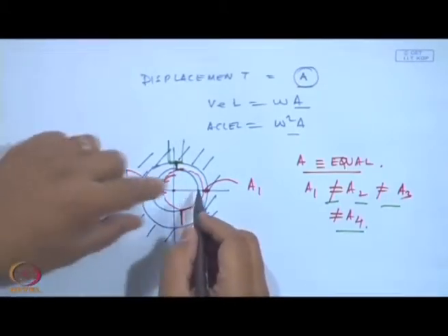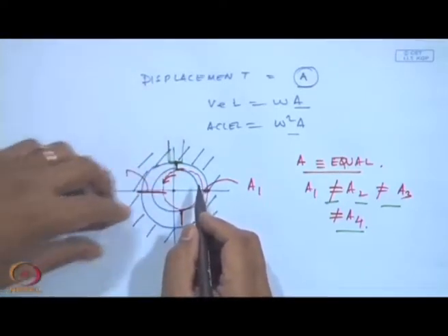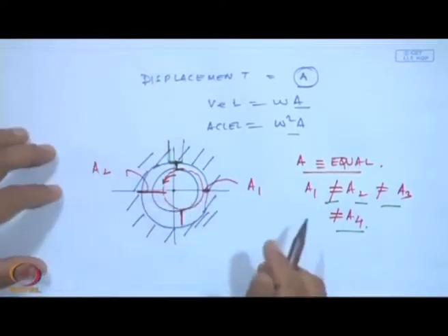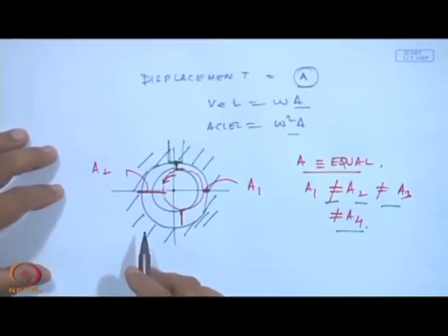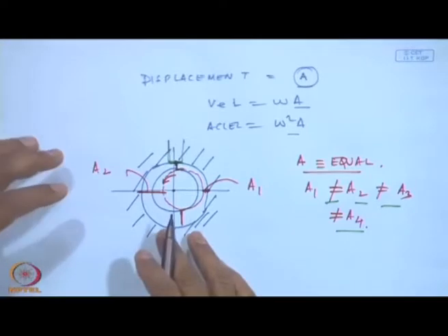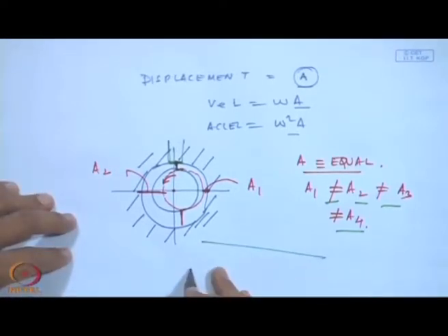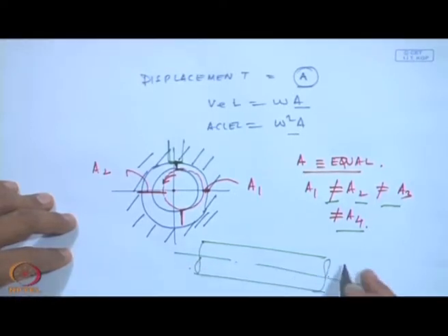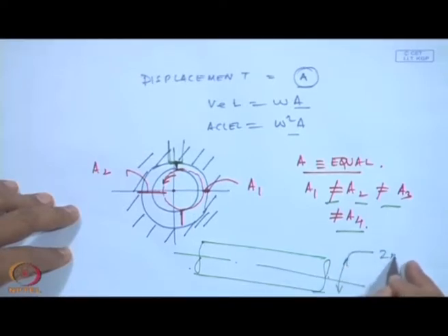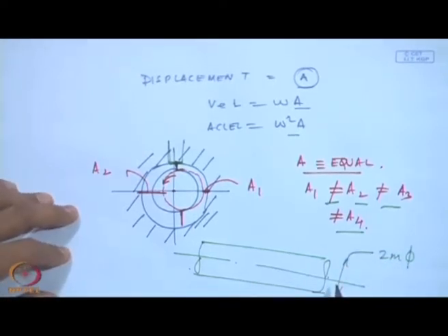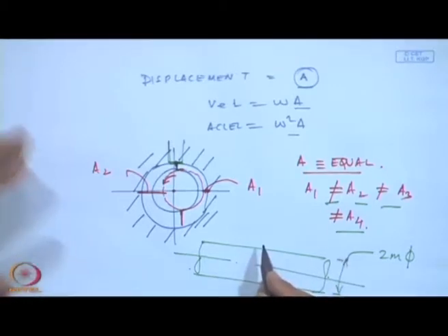Okay. We could be slowly turning the shaft, it may not be powered by a motor, we could be slowly rotating by some mechanical device. Think of a large cement plant where we have a large very long rotary kiln. Kiln could be of the diameter of 2 to 3 meters, the diameter of the kiln. Okay. And this could be about 2 to 3 meters in diameter. So, what happens in such a case, if there is a slight eccentricity, we are going to have problems in the forces, unequal forces, etc.